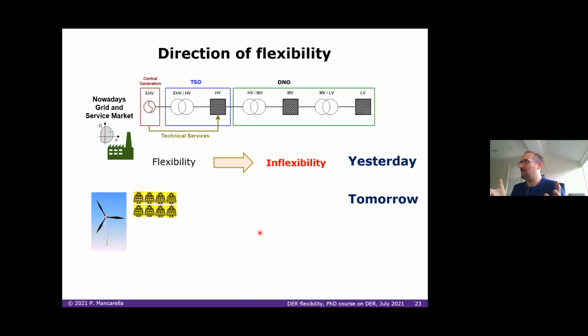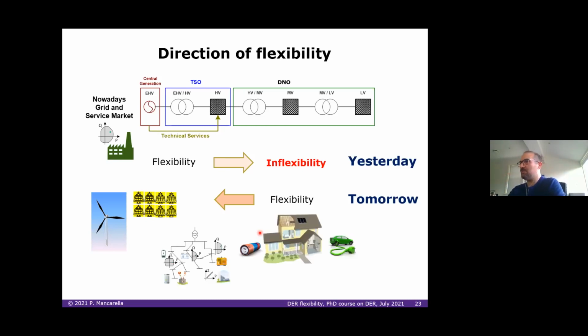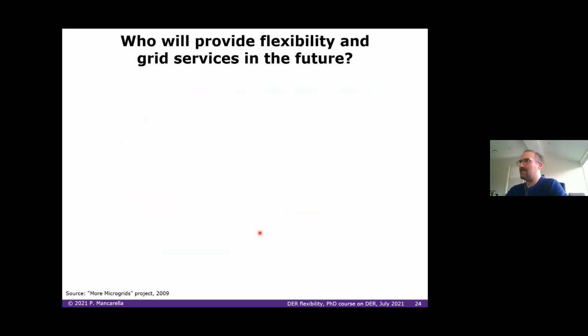Now, actually, it's the transmission system that, because of the variability and uncertainty of large-scale renewables, potentially requires more flexibility. And where is this flexibility coming from? Well, what I'm showing you here is that there is a huge opportunity for this to come from distributed energy resources. So you really change dramatically the rationale and the architecture of the operation of the system, because everything we know about system operations is linked to control and flexibility in more general terms. So imagine that you now have all these new resources that can interact with the rest of the system, first locally and then at the system level.